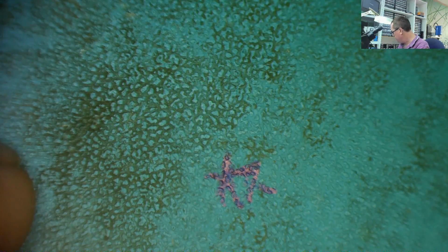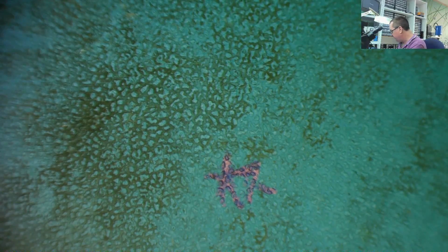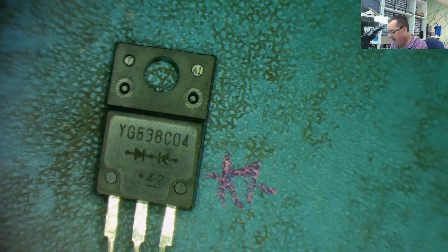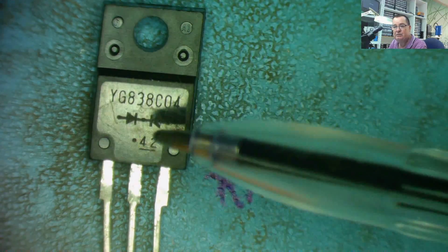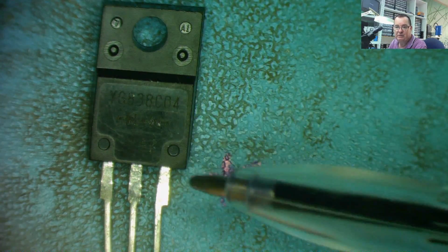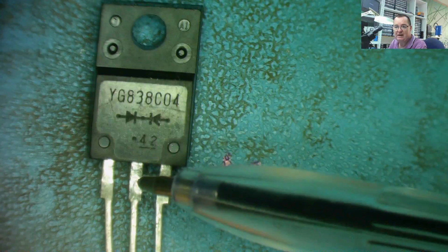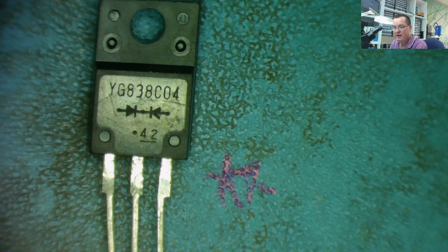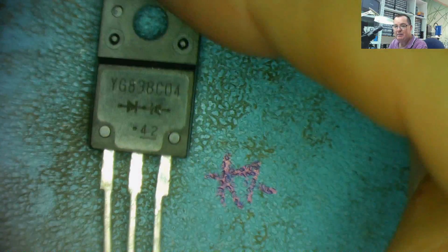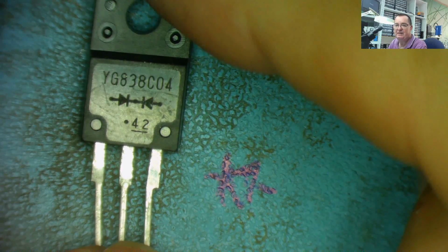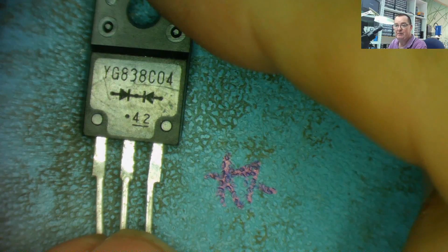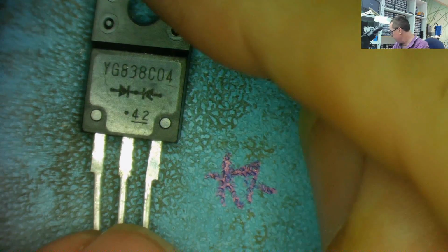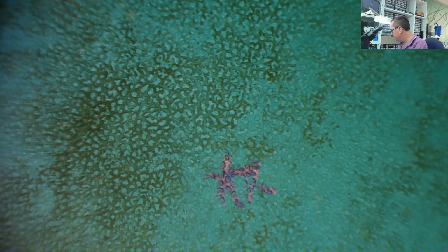We also get diodes like these, and it's quite common. This is actually a diode matrix. This is 2 diodes connected together, and the cathode, the stripe, is in the middle. So anode, cathode, and a pair of diodes called a diode matrix. Often you find these where you get 2 in the same package. This would be called common cathode because the 2 cathodes are joined together. You can also find common anode as well, and you'll find similar things in surface mount devices. These are quite common. You'll find them in power supplies.